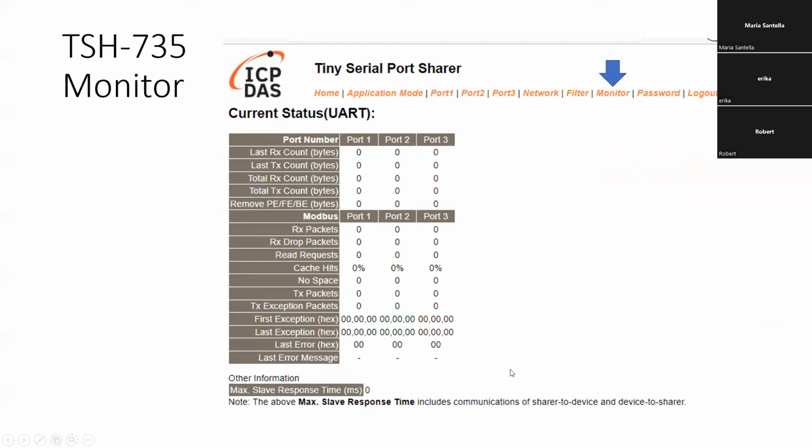It could be something as simple as the baud rates don't match. If you don't see communication happening at all, maybe you have a loose wire, and so on and so forth. But this is a very useful tab for both showing the operation and verifying the operation is happening and making sure there's no communication problems.